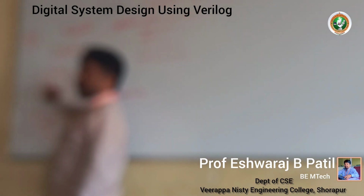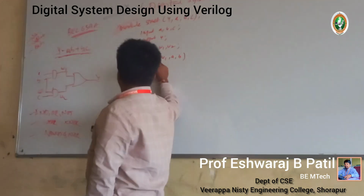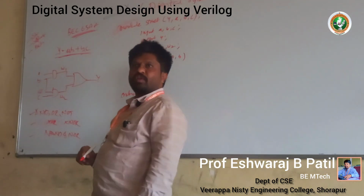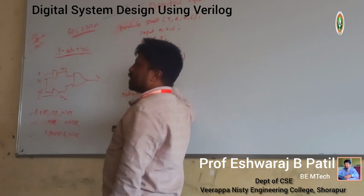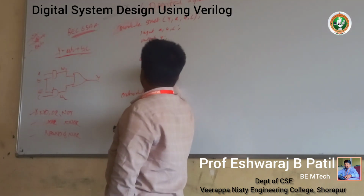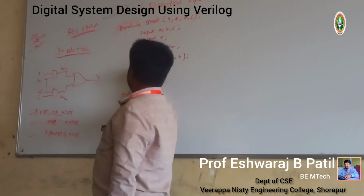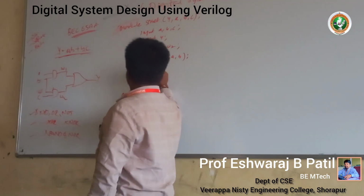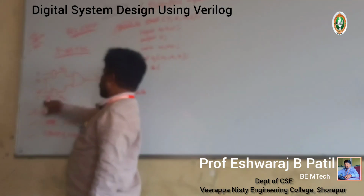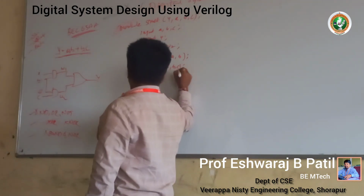First I write the gate name as the keyword and name it G1. The first port is the output, so we write W1, A comma B inputs. Semicolon. The second AND gate is also there, G2, and the output of G2 is W2, with inputs B comma C.